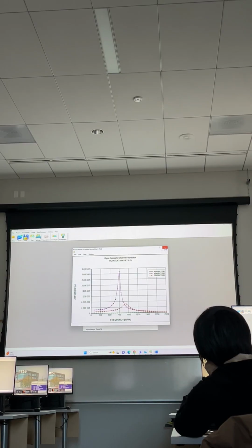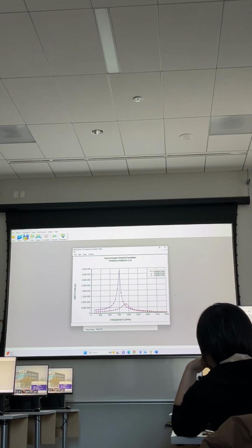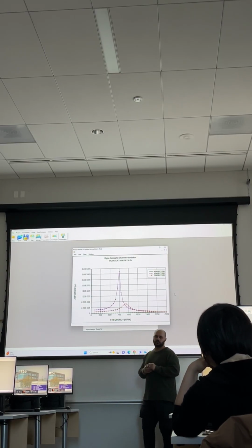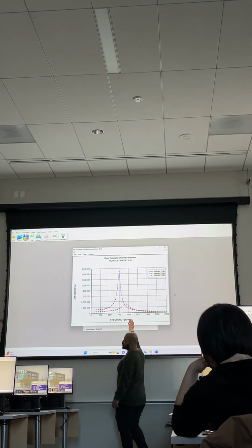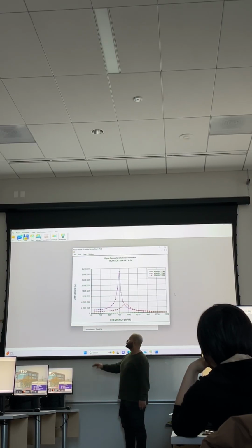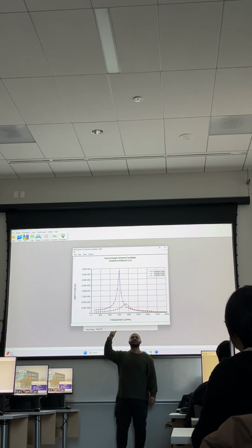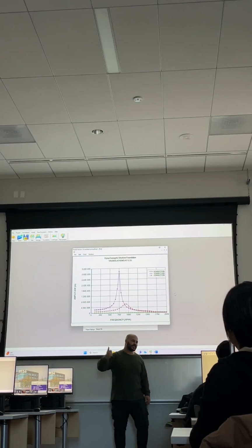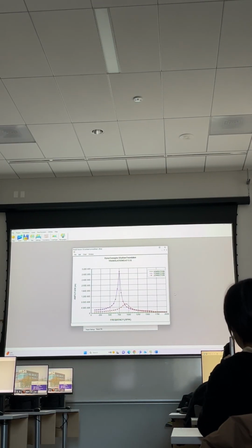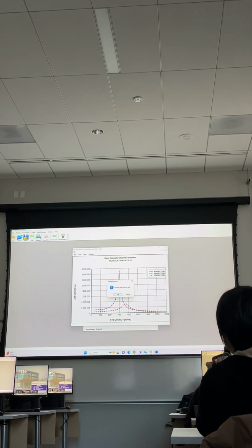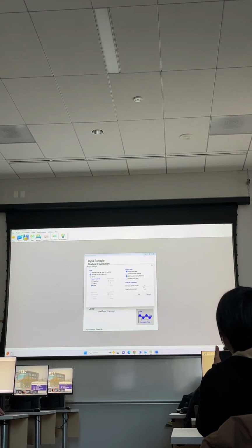Okay, guys. In your assignment, in your project, you may need to do this step to show the professor exactly what the natural frequency of this foundation is. But this is not the actual response. What is the actual response? As I told you, we should go here, edit the settings, and put the damping safety factor as 2.